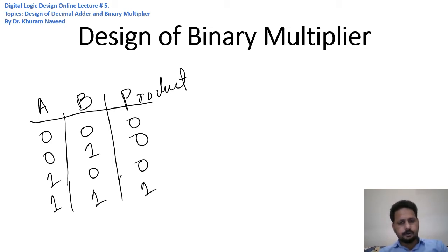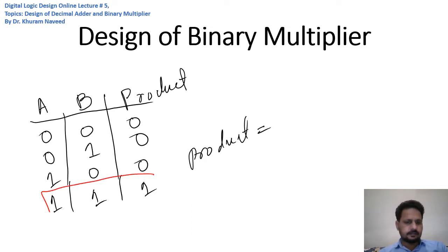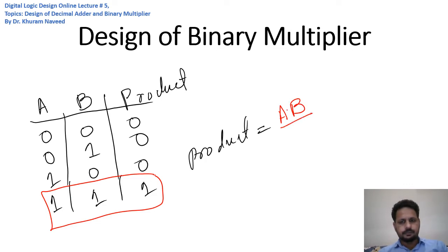So in this case the product or multiplication between two binary bits results in this expression that involves an AND gate between both inputs, right? So we can multiply two bits by connecting them in an AND gate. Once we have this expression for one-bit multiplication, let's move ahead and develop a two-bit multiplier.